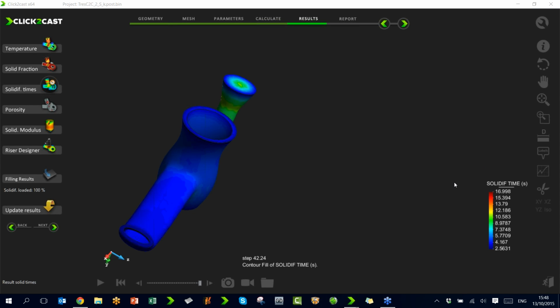What kind of fluid numerics is this simulation based on? Felix Radic is asking about the fluid simulation. I think your question is about the CFD, the fluid dynamic simulation. Currently, we are using a Navier-Stokes calculation coupled with the thermal analysis and computing the free surface of the material using a biphasic flow. So I repeat, Navier-Stokes incompressible fluid coupled with thermal analysis and considering the biphasic fluid to compute the free surface of the material.